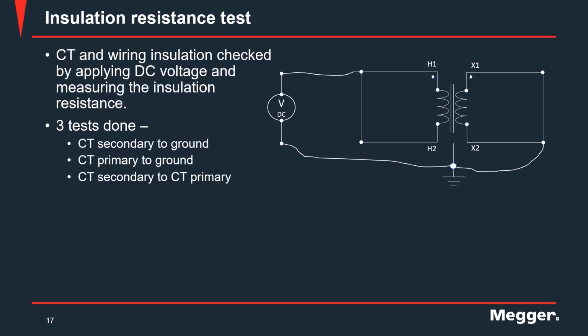Okay, the 45-degree or 30-degree tangent methods are described in IEEE C57.13. These methods were established from experience using conventional magnetic materials, and the significance of these tangent points will depend on the magnetic material in use.